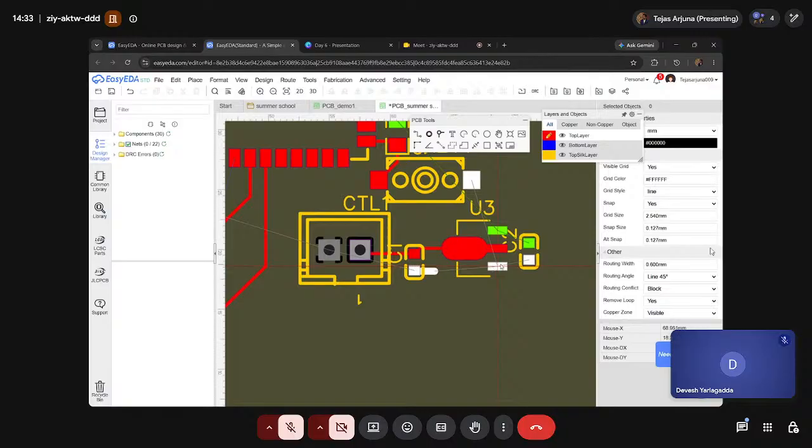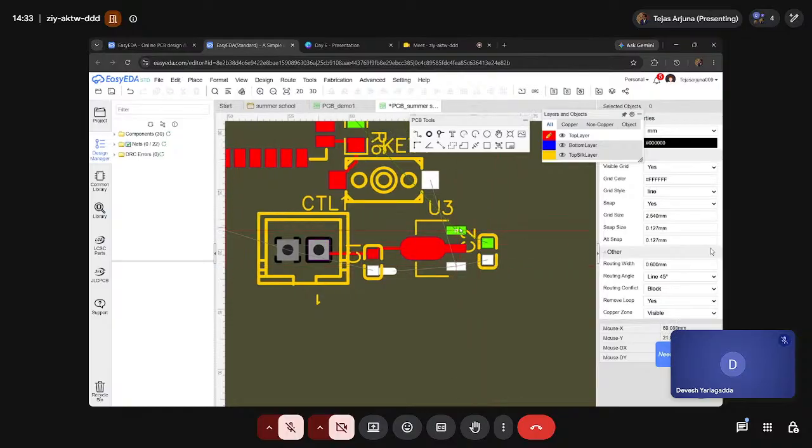For decoupling capacitors alone, connect these traces to the decoupling capacitors and then connect wires through the decoupling capacitors. That is the whole point of using a decoupling capacitor. If you don't use them, there's no point.